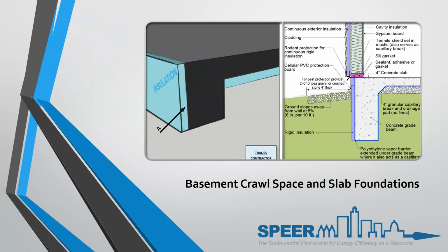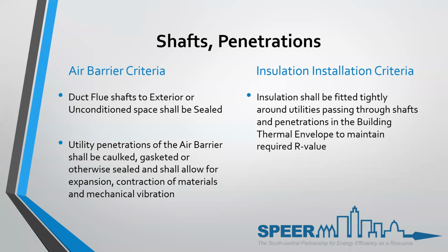So that, if you pictured this, would be 2 feet down, and then you still have to have the sloping away from that. And what they're doing is also having a continuous insulation on the outside, and it's meeting the junction of that where it meets the slab insulation. So there's a continual thermal boundary on the outside of that exterior wall.